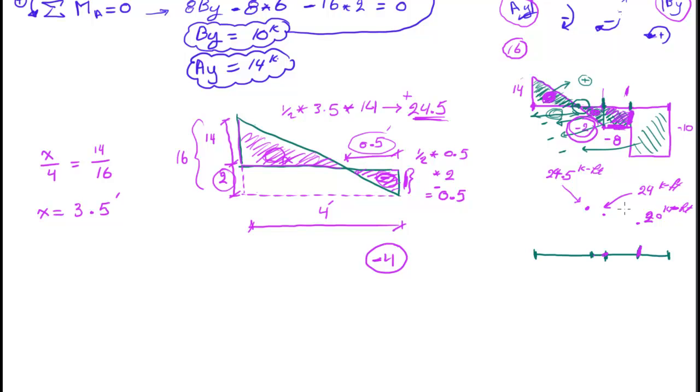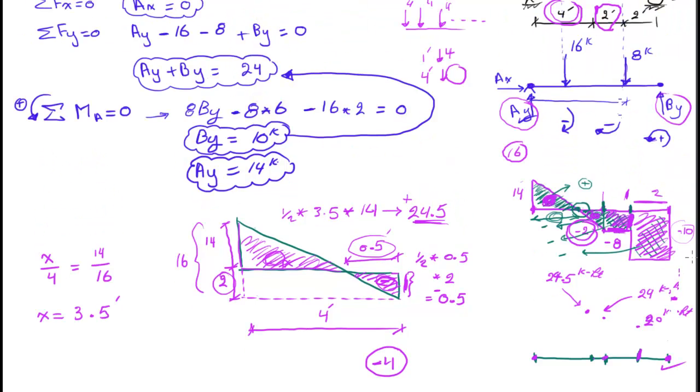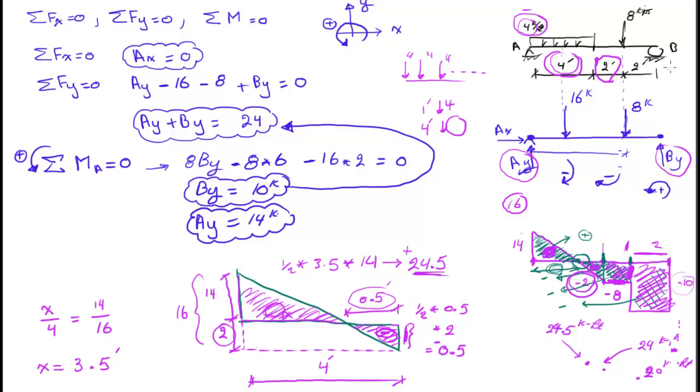Okay, and what about this one? It's again 2 multiplied by minus 10, which is minus 20. I add it to the previous value, which is 20. So minus 20 plus 20 will give me a 0. And that's a check for me that I did it right. Why? Because I was expecting the moment at the hinge and the roller to be a 0. I started up with a 0, got a couple of values, and they should add up to 0 right here, because at the pin support right here there is no moment, or the moment equals to 0.